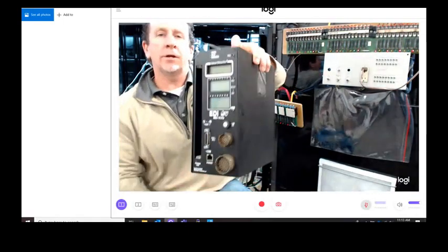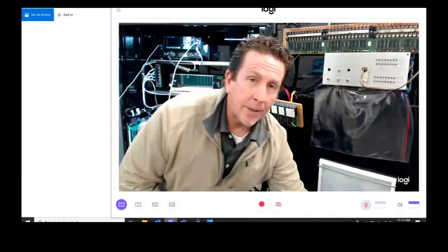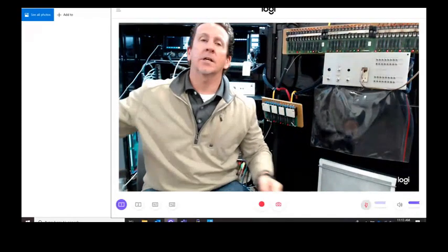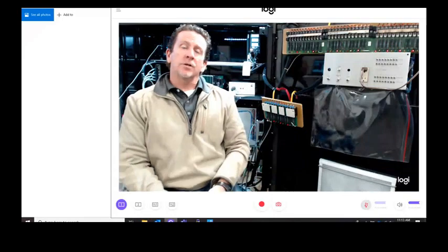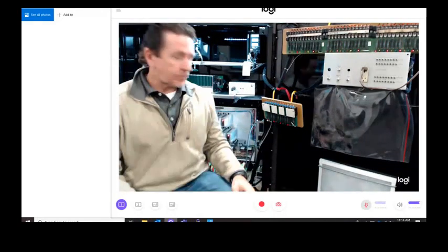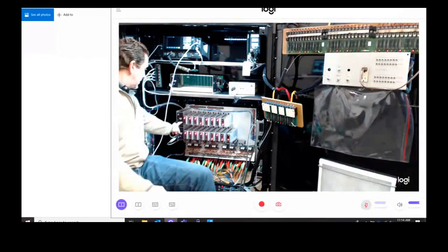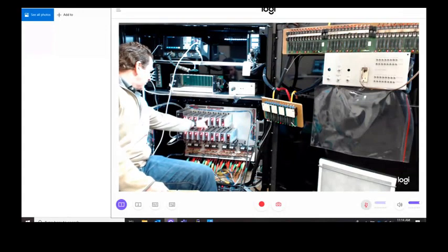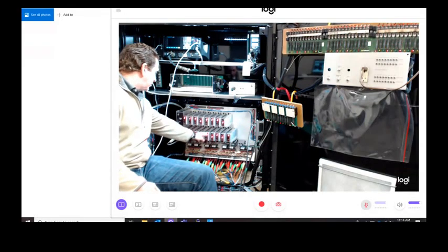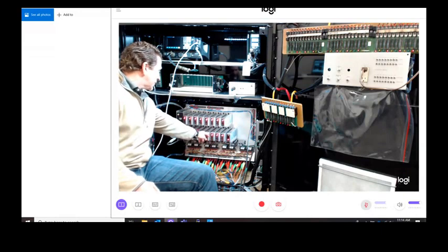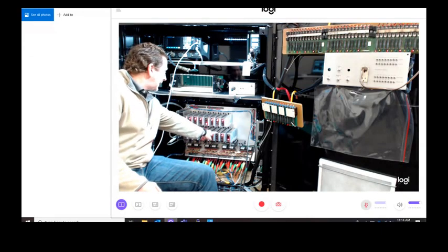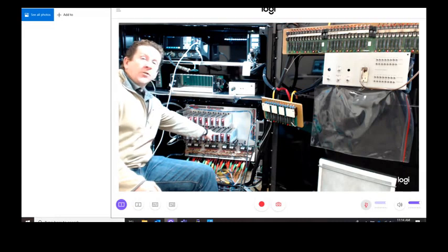One thing to keep in mind when we're using an MMU2, which basically came out when we started using flashing yellow arrows, because that's when, look in the cabinet over here. So for my flashing yellow arrow, load switches 1 and 5 just have a green on them, and they're associated to 13 and 15, which are the other 3 indications on that 4 indication signal.